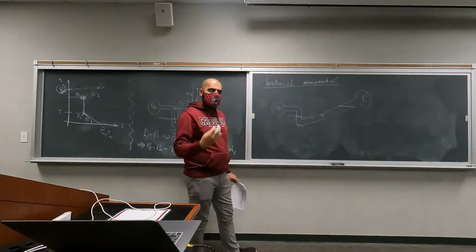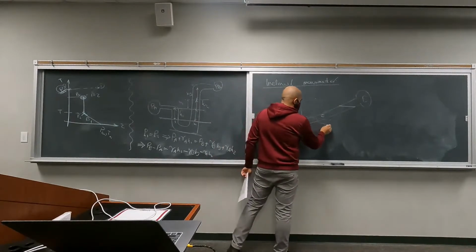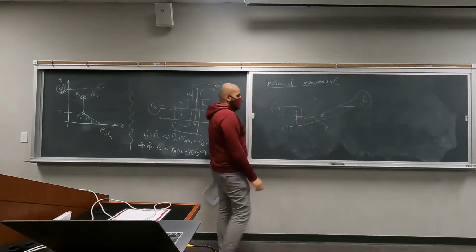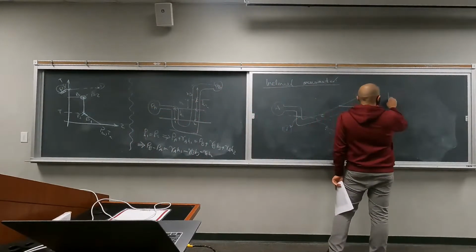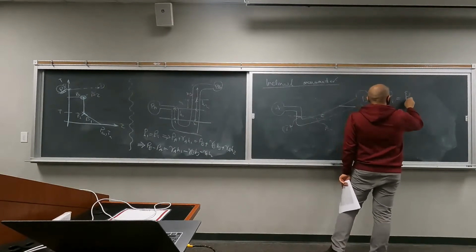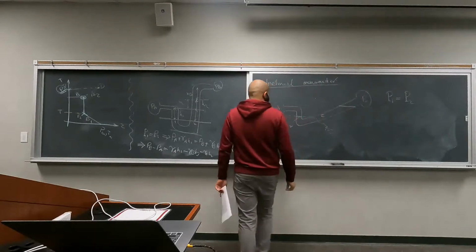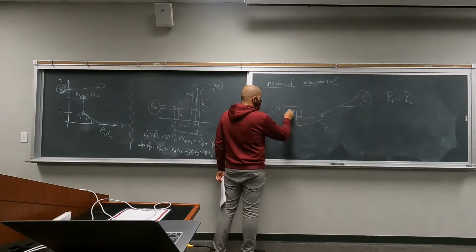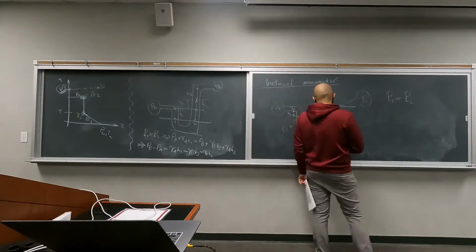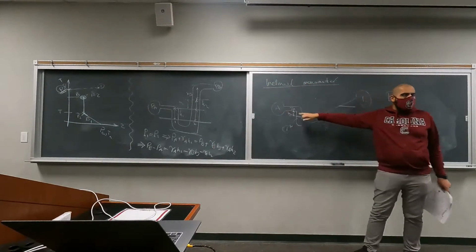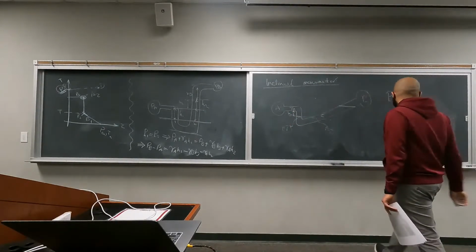The idea was, let's call this point 1 and point 2. The pressure at point 1 and point 2 is the same. So P1 is equal to P2. Okay. Then we want to calculate P1. Let's say this is H1 and gamma of A. P1 is P of A plus gamma A H1. That part we have already seen.